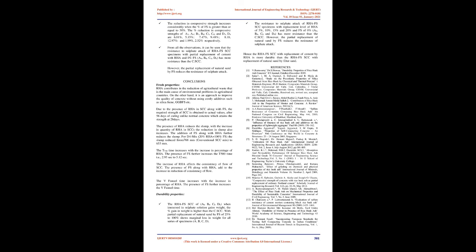The percentage gain in strength in RHAFS-SCC of A0, B0, C0 and D0 SCC specimens were found to be 2.68%, 5.20%, 1.91%, and 0.44% at 28 days curing period, and 4.16%, 1.37%, 6.97%, and 4.68% at 56 days curing period respectively. It is also observed that as the natural sand is replaced by FS in RHAFS-SCC, A1-A4, B1-B4, C1-C4, D1-D4, immersed in 5% Na2SO4, the strength decreases, and the reduction in strength increases with increase in percent of FS.